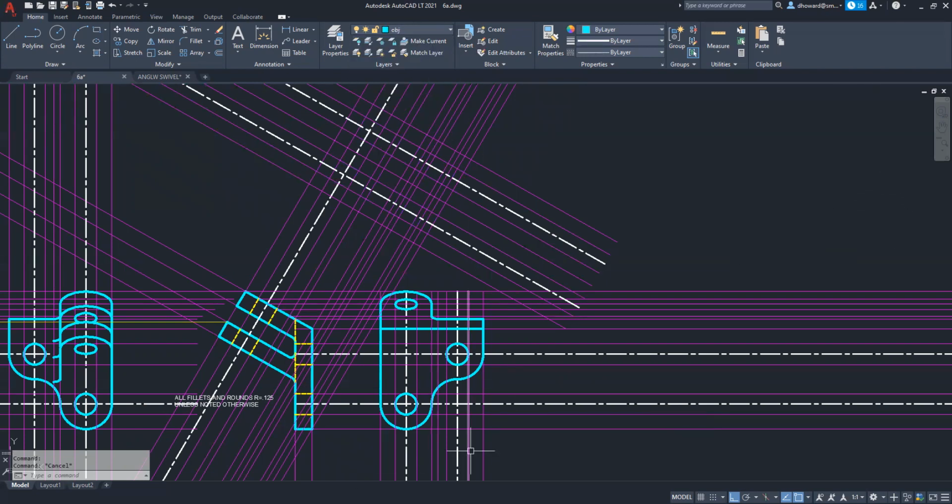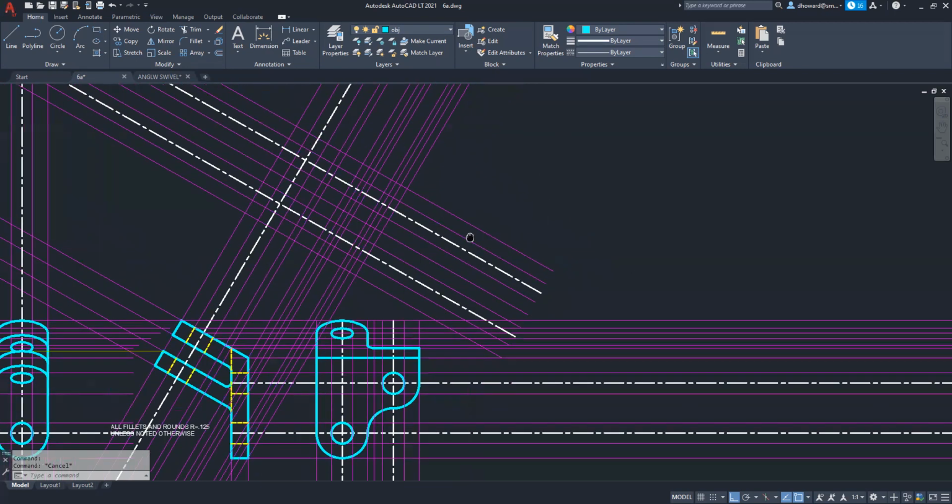So we could have drawn a bisecting transfer line here, bisecting this angle between here and here, which would have been 30 degrees, and we could have projected these lines upward and then off of it if we wanted, but instead we just did the offsets. And it was pretty easy to do those offsets, again, because there weren't very many. Okay, we have pretty much all of the construction lines we need for this, I think. So let's get to it.